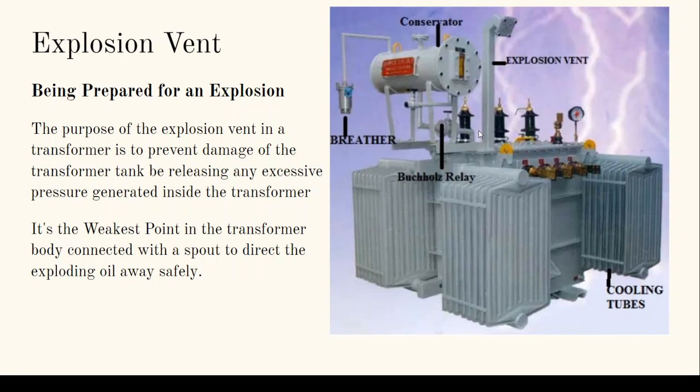So there's turns, first coil set between 1 and 2, 2 and 3, and 3 and 1. So this is your delta connected primary winding. This is your star connected secondary winding, which has a neutral also. So this is why you have 4 terminals on your secondary and 3 terminals on your primary. Then you also have your oil temperature gauges, you also have your conservator and other parts. We'll look at them in detail.